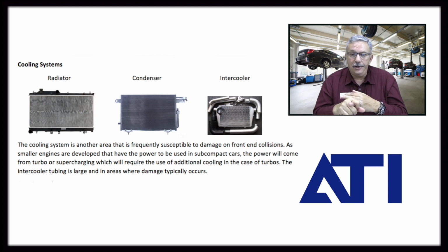Road testing a vehicle where you've changed mechanical parts, it's a must. Because unless you do that, how do you know? You don't want to just give the car back to the customer, the customer takes the car out, has some kind of a failure mechanically, and it was something that you could have easily seen in a road test. That doesn't look good for the quality of repair that the shop has done. So then they're going to question everything. So again, the road test is a pretty important part of doing any of these mechanical operations that we've been talking about.